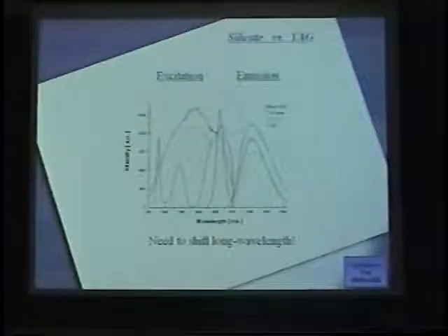This one is a typical example of what kind of phosphor we need. For instance, blue, Nichia's patent. They use a 465 nanometer chip here. This one is the emission from the chip. So for the phosphor, this phosphor has to absorb a lot of photons in this region. Then the phosphor also has to emit the color that you want, in this case orange. Then this blue color plus orange can make a white color.